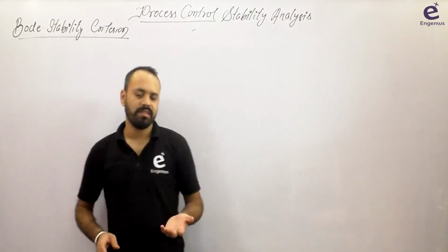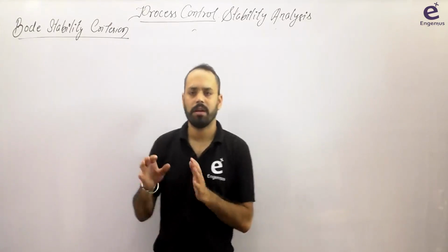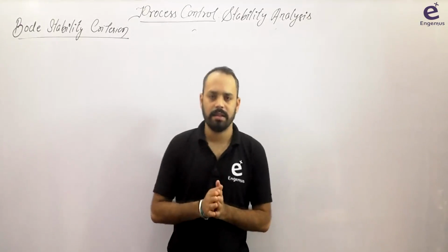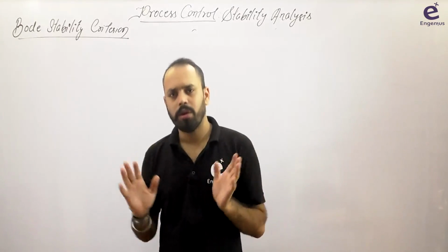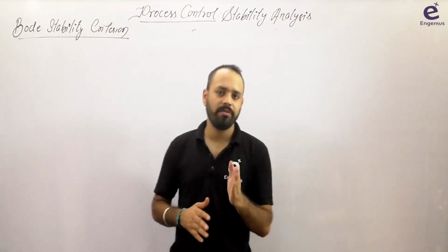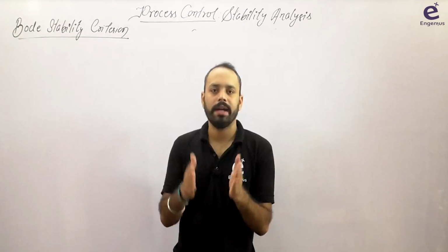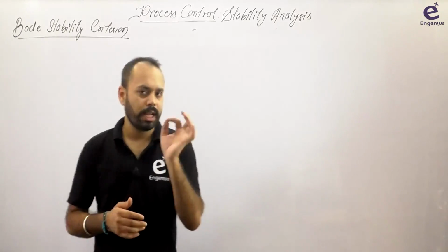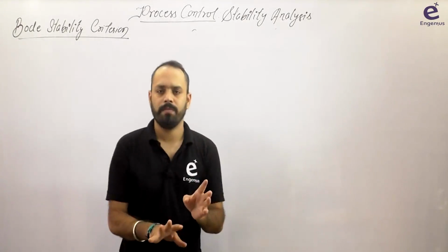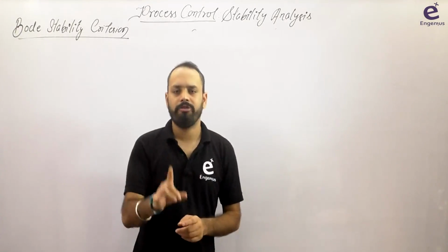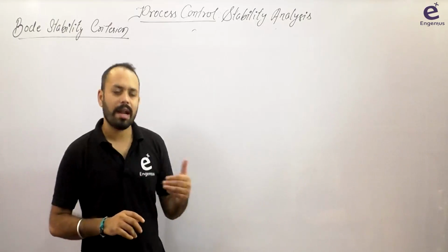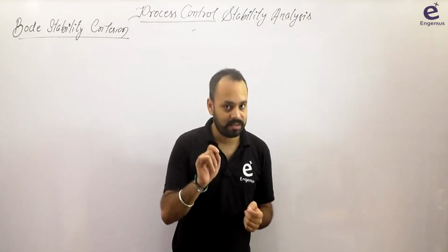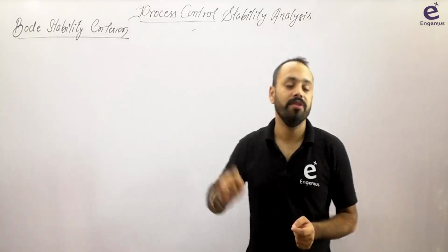When a crossover frequency can exist and when it cannot exist, I hope we can easily understand this. So I wrote two very important lines: in the absence of dead time, the range for phase angle was till minus infinity only with dead time. So if dead time is present with any system, there will definitely be a finite crossover frequency, and there are chances, please note chances, that the system can be unstable.